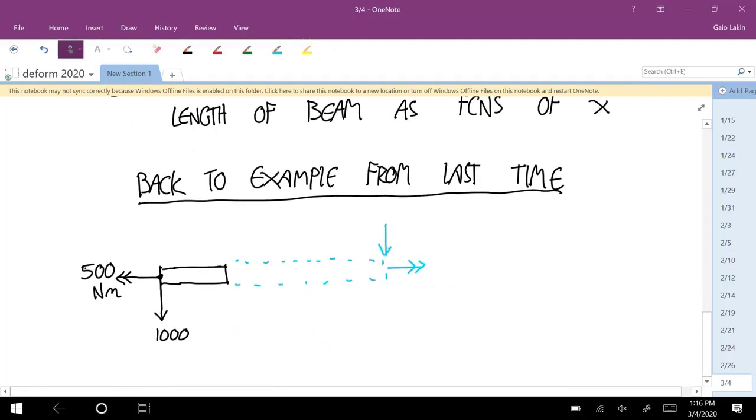So we have a tension T, a shear force, and now our default direction is down, V, although it still has the same information in it that the y component of a force vector would. Then the couple, that's the component of the moment about the z-axis. We call that capital M. And then finally, the internal torque, fancy T.